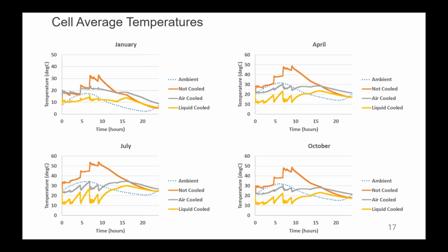And the main consideration when you're looking at something like pack lifetime is actually what's happening when the vehicle is not being driven and is sitting in a hot soak scenario outside where the sun is beating down on it and you have high ambient temperatures and so forth. And also what happens during fast charging when the coolant system may or may not be running.